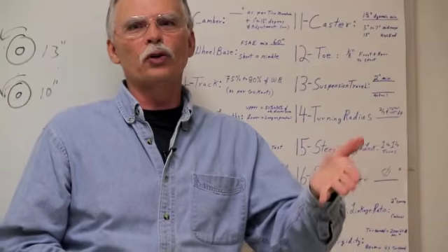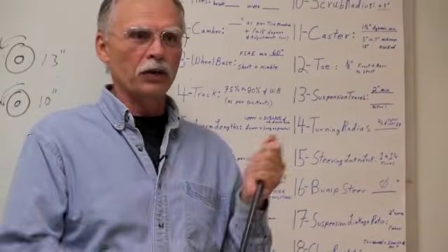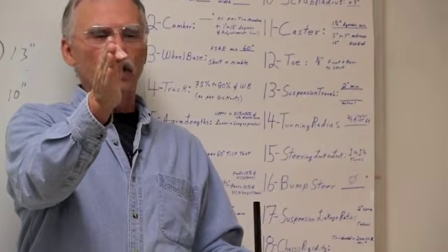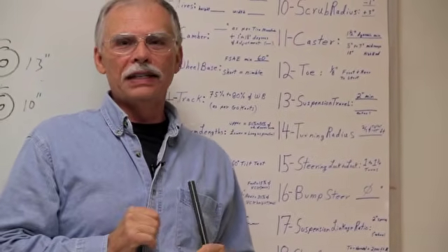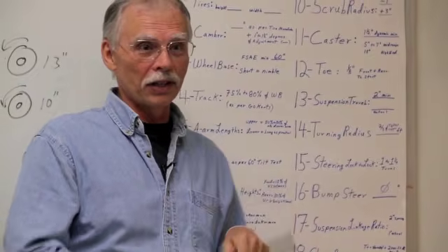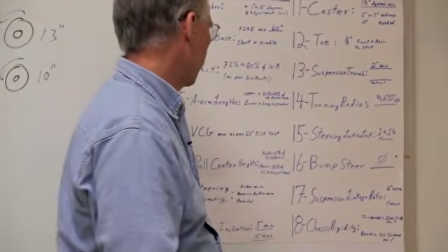This is sort of your grade. If it's very, very low, you did a great job. If the wheel, as it hits the bump, suddenly points over away from the intended direction of travel, well, that's not good. That means the car is going to steer itself when it hits an undulation in the track.